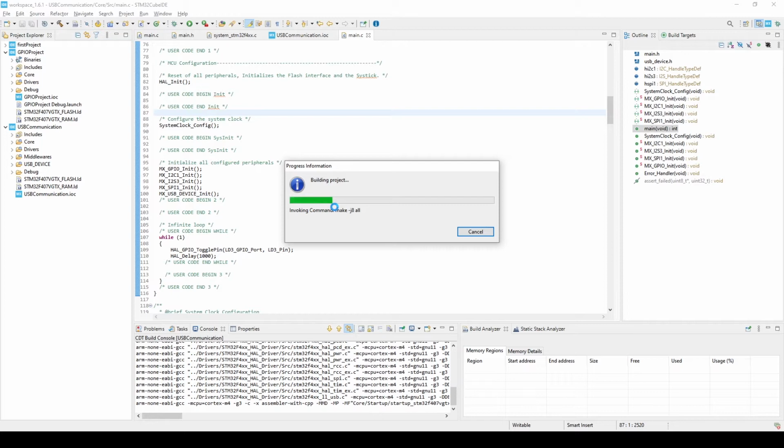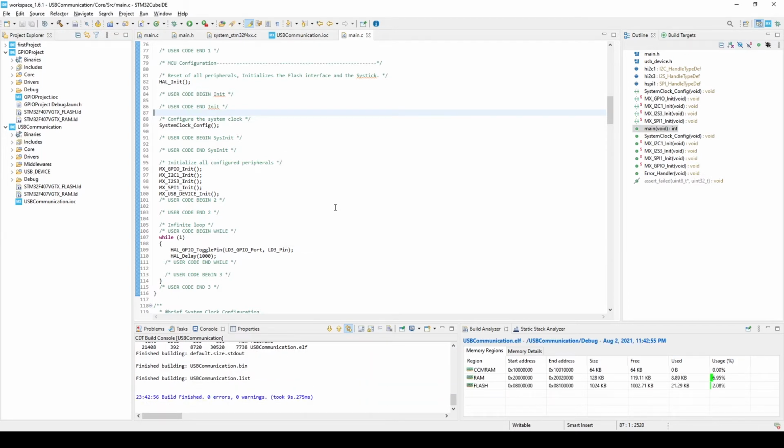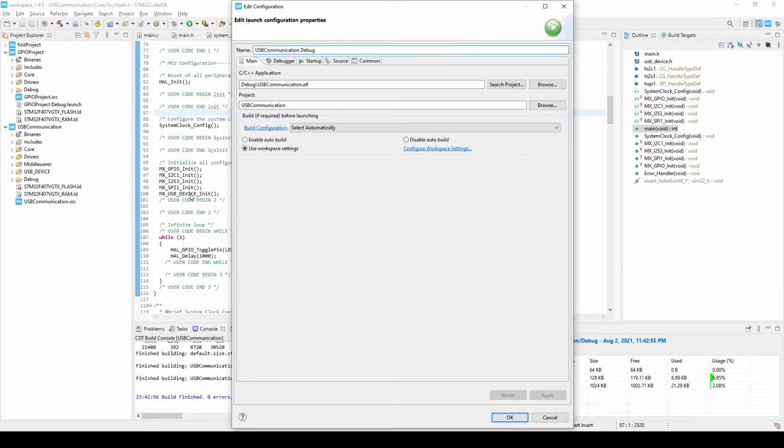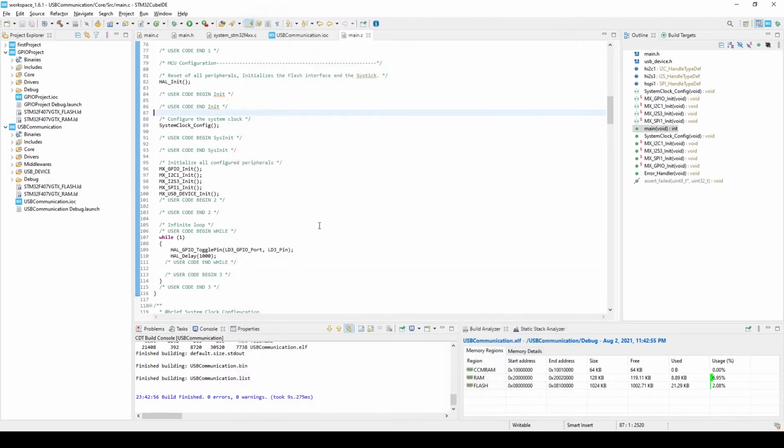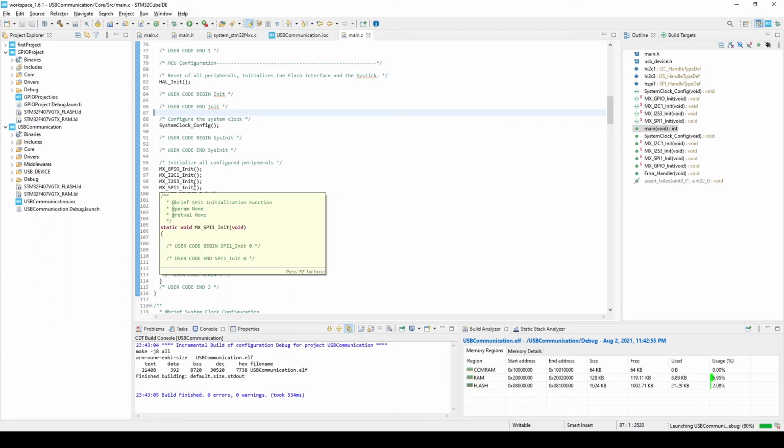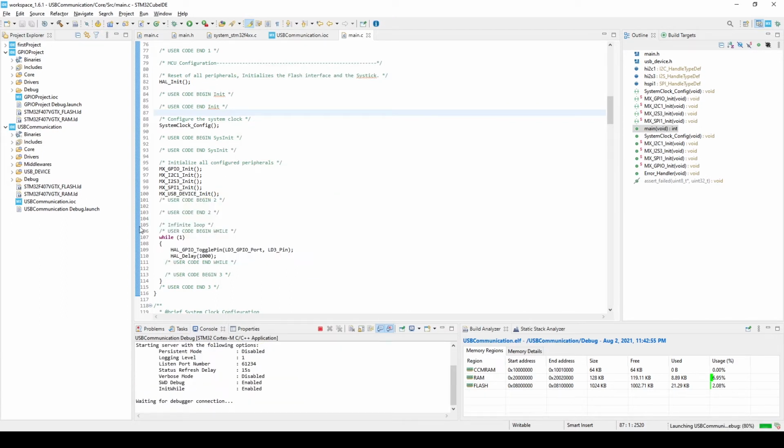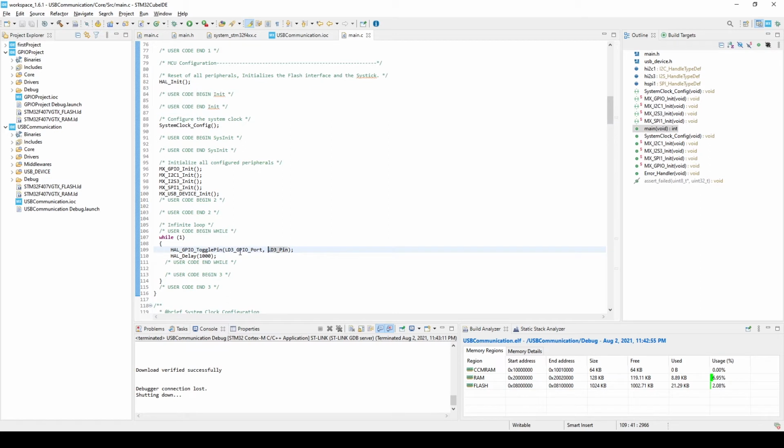For example, if there is a soldering issue on the USB side of your board, your microcontroller will probably get stuck here, and you can use the debugging tool to see where it's stuck. That's one of the cases I want to rule out. If I can see the LED blinking now, it means the code was okay. I can see the orange LED blinking, so everything goes okay.